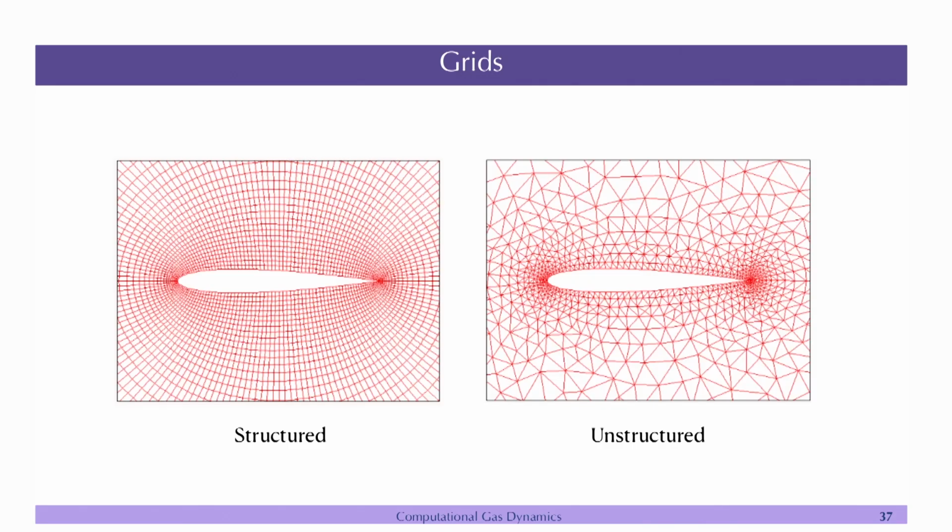So, this is the example of a structured grid on the left and you have an unstructured grid on the right. Just to show you, if you look at the grid here, you have a very nice distribution of the grid, and this is a kind of O grid that I am showing here. So, what is an O grid? Basically you have an airfoil here and you made an O shape which is the external boundary, and what you did is fill in elements like this, till the last boundary, and then you also had these elements,